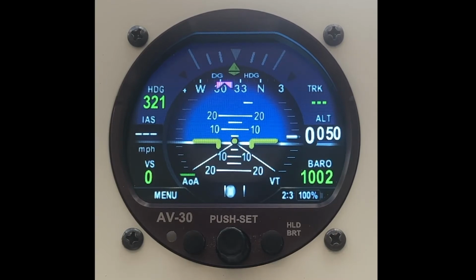It's a different set of data around the outside as I have set it to demonstrate. So we've got vertical speed in the bottom left hand corner. We've got IAS in miles per hour here. We've got the heading, which is derived from the DG heading. It works very much like an old-fashioned gyro-driven instrument, in as much as you datum the heading to a known heading from either a magnetometer, a compass, another device in your aircraft, or indeed even just lining up on a runway and taking that to be the QDM to be the correct heading.